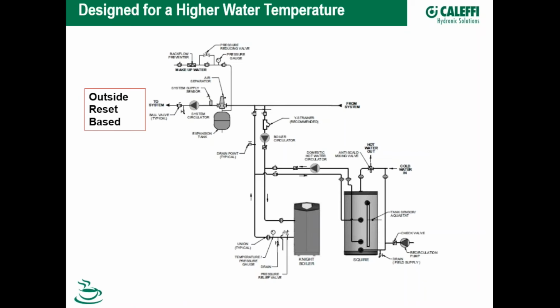Outdoor reset, the temperature changes over the heating season. When I do an indirect water heater, it's all about set point. What water temperature do I need to maximize the performance of the water heater, or meet the needs of the building for that water heater?